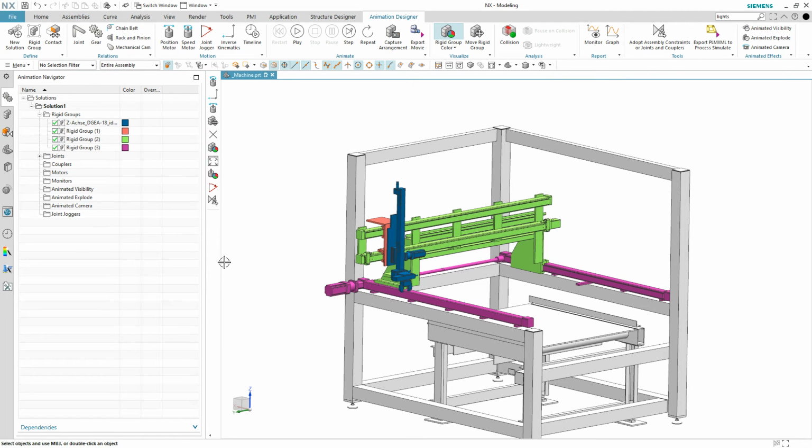Now it's time to add some motors. We're going to spend more time getting the sequence of operations defined, but right now let's just get some basic motors going and see how this thing reacts to that. We've been using speed motors in the previous examples. This one will be using a position motor. A position motor is an intermittent motor. It goes a certain distance or a certain speed or a certain time and then stops. You could have it start up and do it again, but it has a defined start and a stop, whereas a speed motor just runs continuously like a fan.